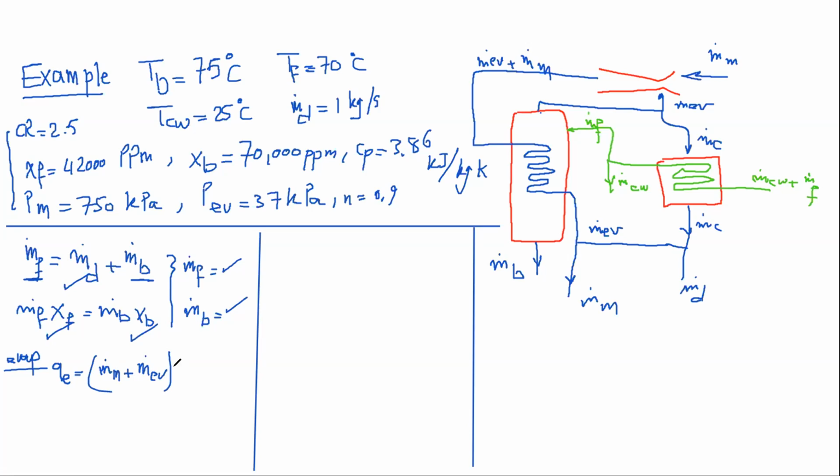This is the vapor which is coming in, and it's going to condense here, times h_fg. Actually, what you do is go to the thermodynamic tables to obtain the value of h_fg. But you will see that we don't know the temperature of the steam. Yet the pressure is not given.